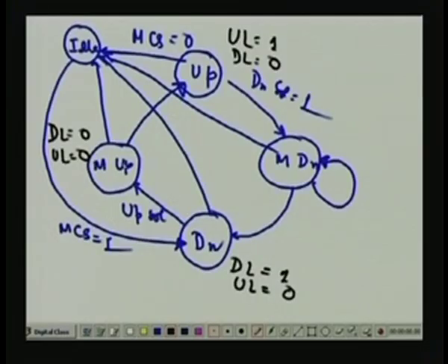So now one has to ensure somehow that the specification that you give for the system is met: first the up solenoid is exercised and it is held till it goes to the up state, and then when it goes to the up state, the down solenoid is exercised. So this is the desirable cycle of the machine. Some device has to compute when to apply this up solenoid and when to apply this down solenoid, and it is the controller which is going to do that.